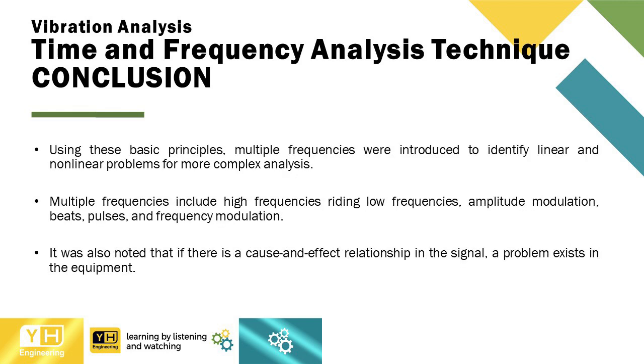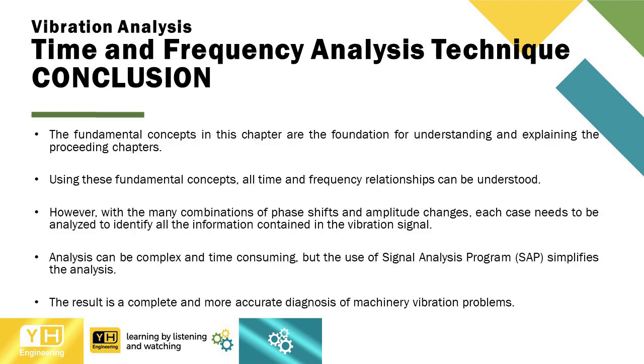Using these basic principles, multiple frequencies were introduced to identify linear and nonlinear problems for more complex analysis. Multiple frequencies include high frequencies riding low frequencies, amplitude modulation, beats, pulses, and frequency modulation. It was also noted that if there is a cause-and-effect relationship in the signal, a problem exists in the equipment. The fundamental concepts in this chapter are the foundation for understanding and explaining the preceding chapters. Using these fundamental concepts, all time and frequency relationships can be understood.